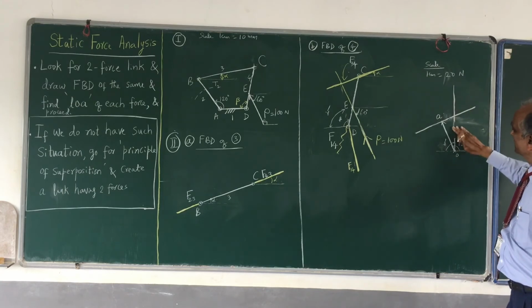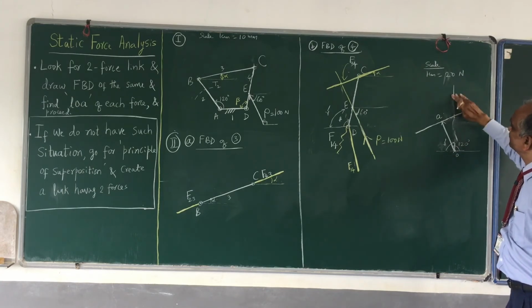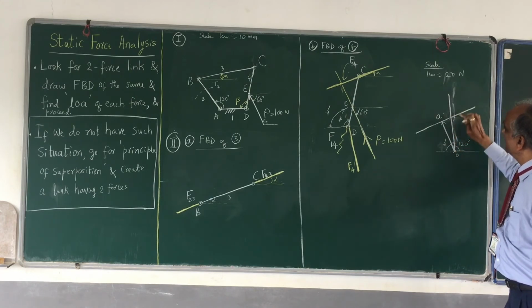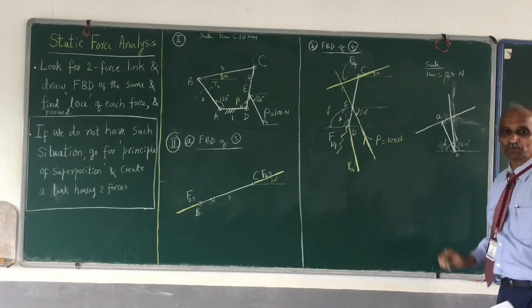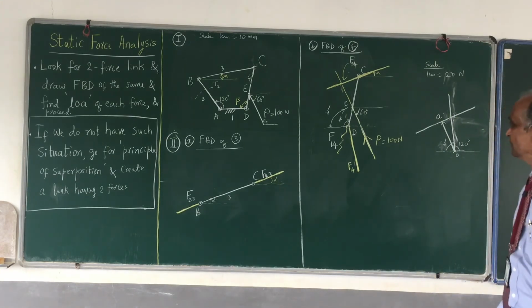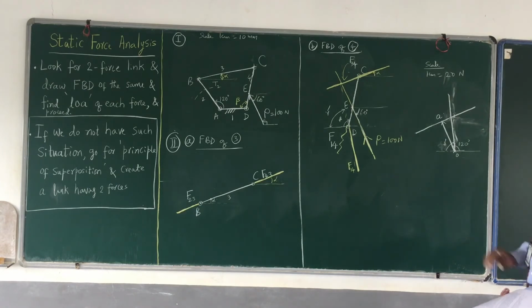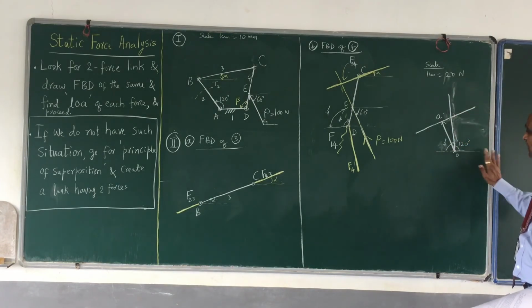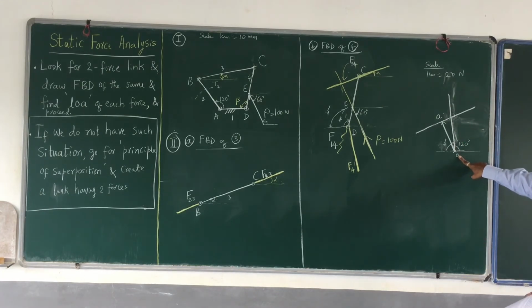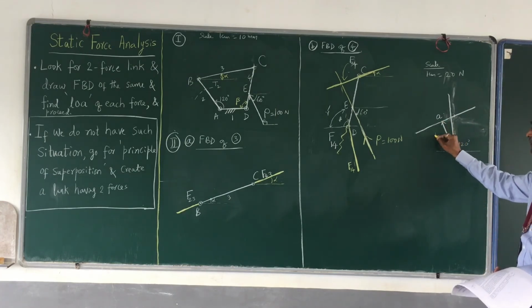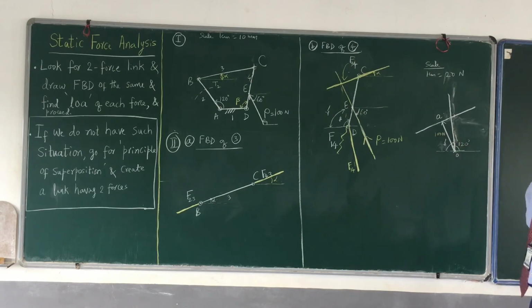So slightly inclined. This is what I was telling initially. I am only indicating the procedure and you will be drawing it exactly and then you will come to know it. Now let only the forces be dark and all other construction let it be light. This is your starting point. You have drawn OA. OA is equal to P, which is equal to 100 Newton.